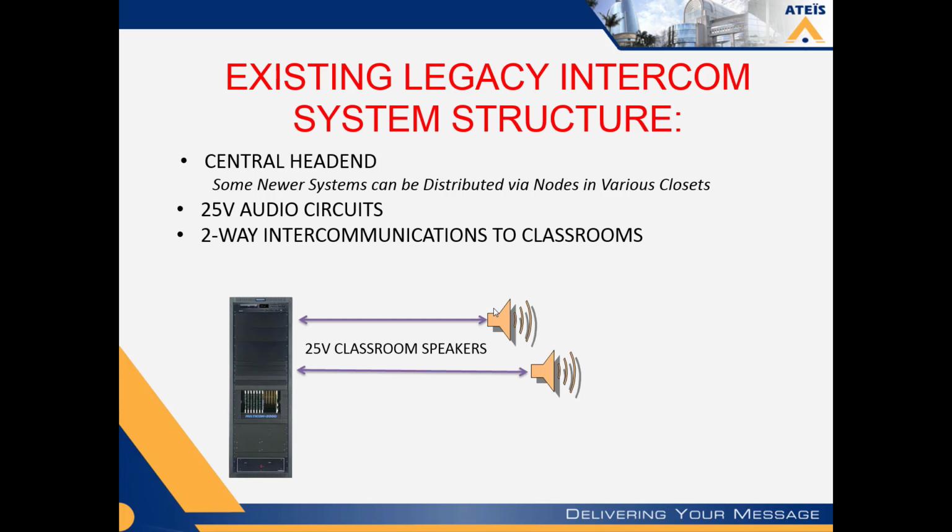All these speaker circuits used on these systems are usually 25-volt audio circuits. I would dare say 95 to 99% of the systems that are still out there are all using 25-volt audio circuits. Even the ones today that are IP hybrid-based are using 25-volt audio circuits. There are very few out there that don't use 25-volt systems.